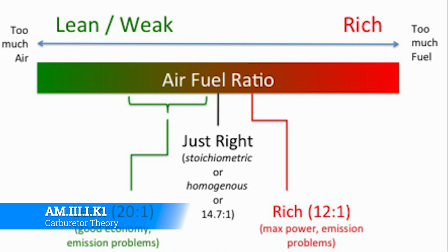If you have too much fuel, that leads to a certain set of circumstances. Worst case scenario, it just doesn't light off at all because it's basically a big jug of fuel with an electrical spark going and not enough air to combust it. Or on the other end of the spectrum, where it's way too lean and weak, you just won't have enough fuel in there to light. Just like if I lit a match in the middle of this office right now where I'm recording this, nothing would happen because there's not enough fuel in the air to cause it to combust. So we have to have that Aristotelian mean between fuel and air, the right mixture to make it go off just right. Now, what does that look like?